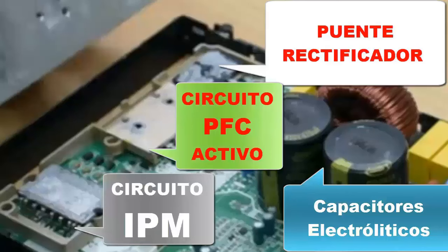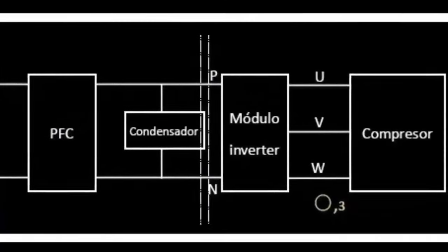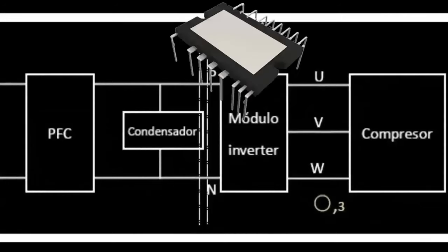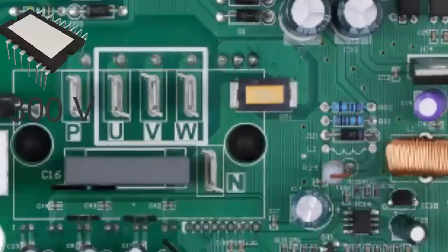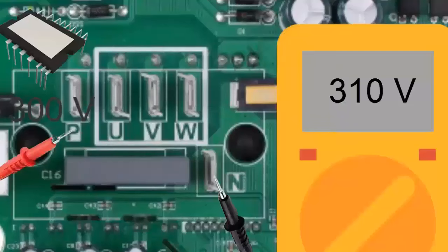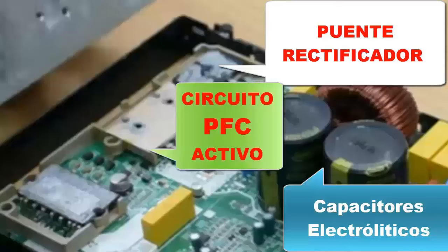Under normal conditions, the DC voltage between the P and N terminals of the IPM electronic module should be approximately 310 volts in standby mode and 380 volts when the unit is in operation. If the measured voltage is less than these values, a PC10 error will be triggered. If the supply voltage to the IPM electronic circuit is not correct, the fault should be focused on the PFC module and the rectifier bridge.